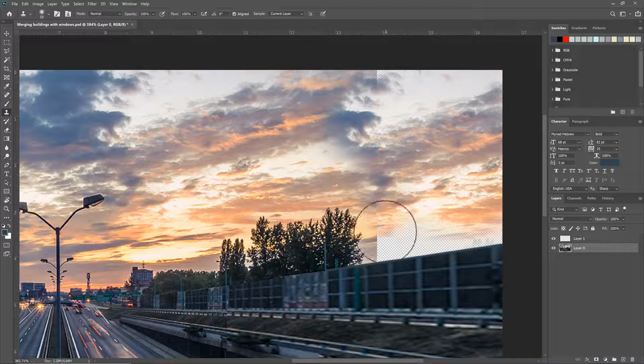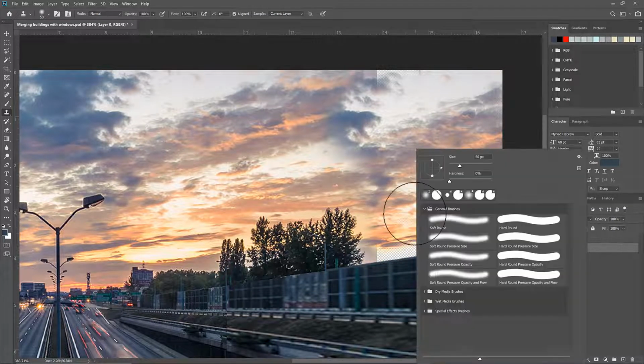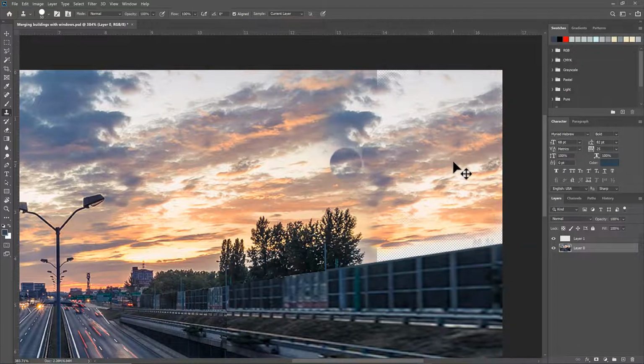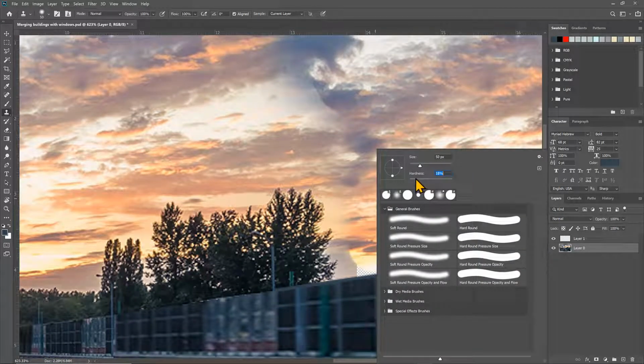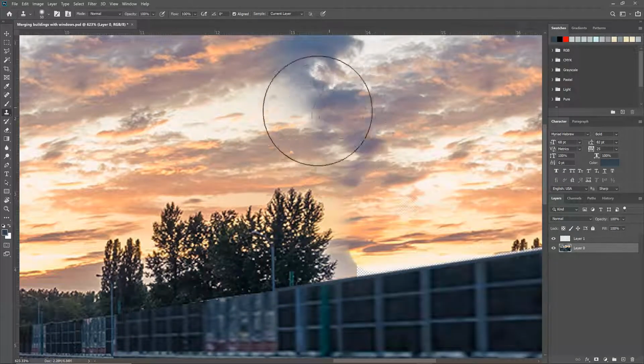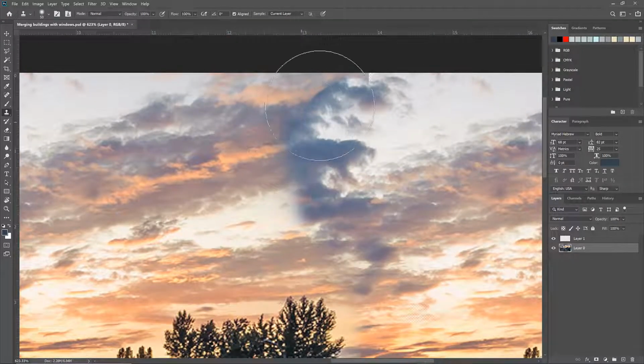You can see it's pretty simple, straightforward. Right mouse button, hardness, so no fuzziness, at least just for this area, and then hit shift and left mouse button, so it's gonna copy on all of it. And then here you go back and reduce the hardness, so it would be kind of fuzzy.